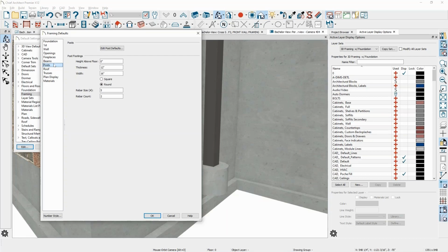No, that's all right. I've found it, and I've actually opened up with a post, so it's given me that width of 400 and the thickness under the default. Yeah, so then you can also control the way your footing comes in, whether it's round or square. Awesome. And then save that in, if that's something you do all the time,